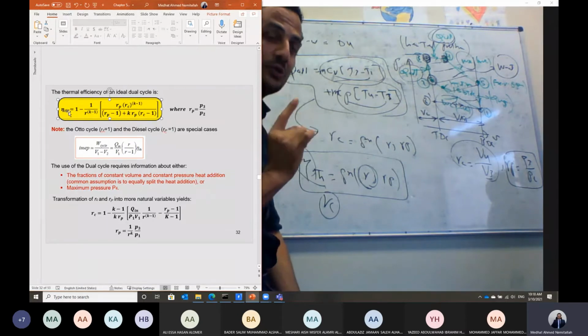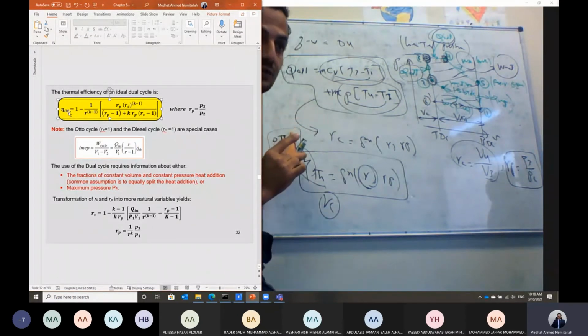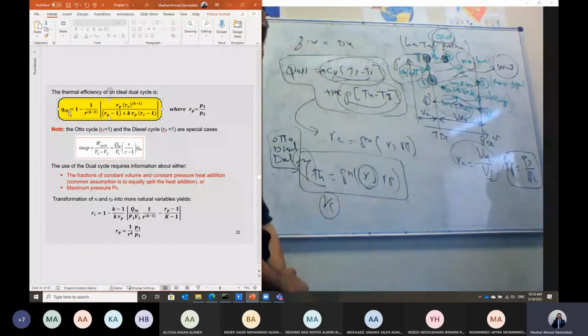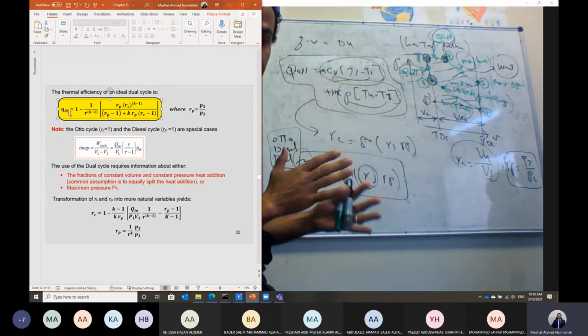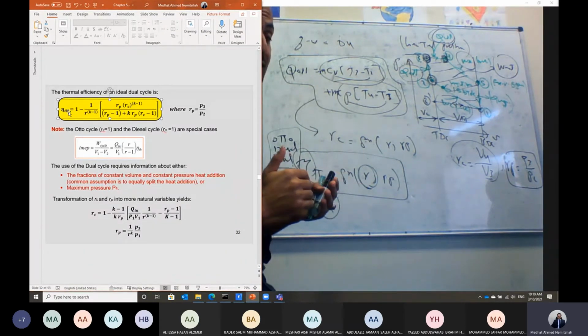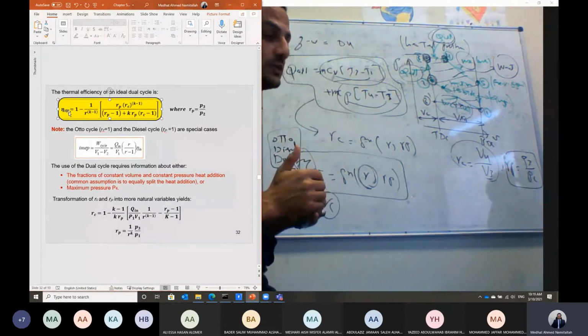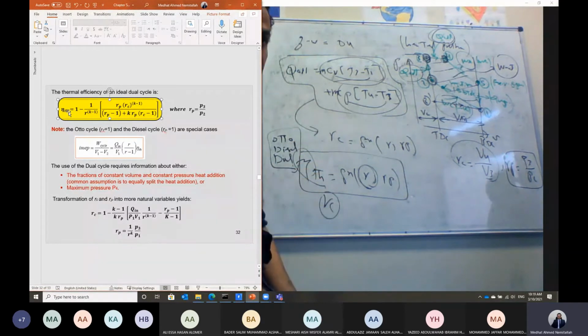But this is the only situation in which the efficiency of a gasoline engine working on Otto cycle is greater than the efficiency of a diesel engine, when we have the same compression ratio. But as you know, diesel engine and gasoline engine do not intersect in the operating compression ratio. Usually gasoline engines are limited by knocking, so they cannot go above compression ratio equal to 11. But in case of diesel engine, we cannot actually work at compression ratio less than 15, and that has to be higher in this case. And that's why the diesel engine at any other condition should result in a better efficiency.